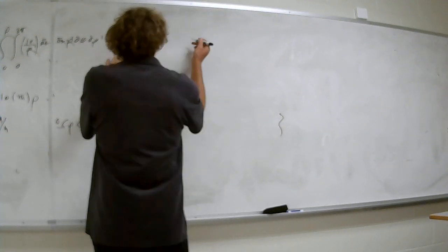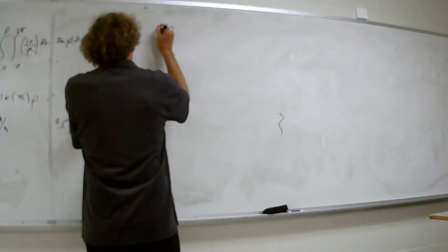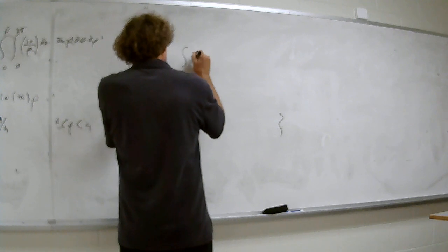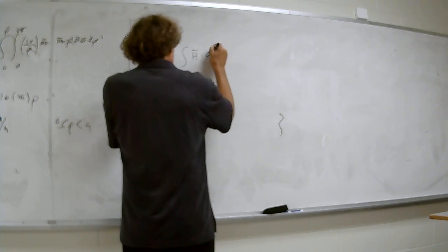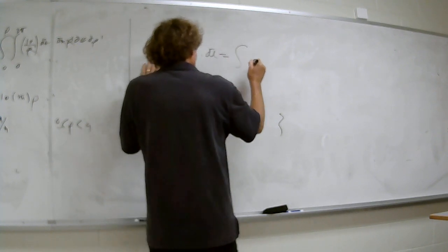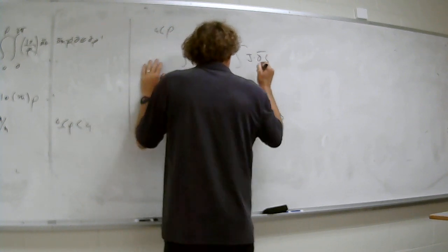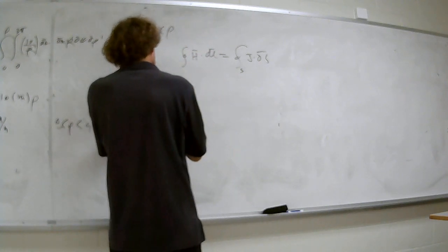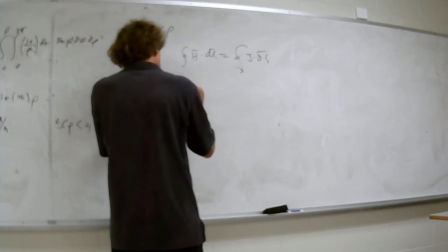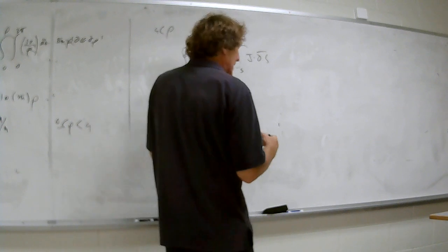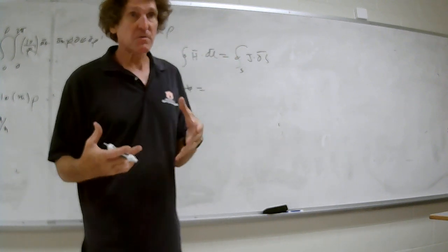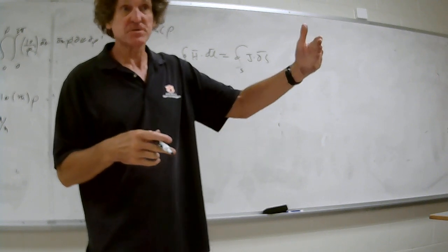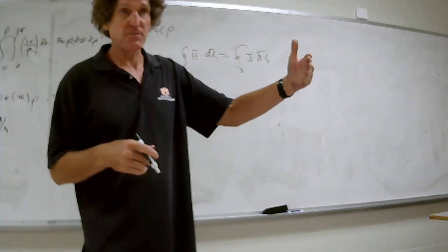So now for rho greater than A, again, it's always smart to put this down first. The integral of H dot dl is equal to the integral of J dot ds over the closed surface. Here, this is still 2 pi rho H phi. And over here, now we're outside the region where the current exists, so we can only integrate the current density out to A, because the current density beyond that is 0. Do you all follow me, class?